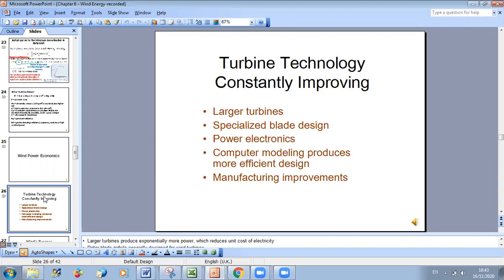Yes, I'm sorry for being late with my question. I just wanted to ask about the limit, is it so that the turbine doesn't stall? No, the limit is that if you want a flow over the turbine, when you have a flow entering you can't keep all of it inside. You have to have a continuous flow. Air should go out and then a new part should go in. To maintain this flow over the wind turbine, you should have a certain loss of kinetic energy. Otherwise there is no flow. Okay. Yes. Okay.